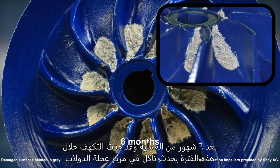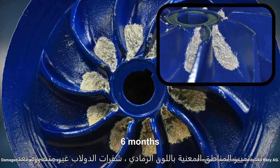After 6 months of operation under cavitation, material has been eroded in the center of the wheel. The respective areas are highlighted with grey color. The impeller blades are undamaged.